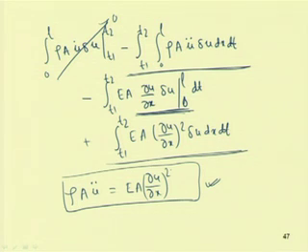So, in today's class we have taken several examples using Lagrange and Hamilton principle to derive the equation of motion. We have derived the equation of motion for a single degree of freedom system, that is the simple pendulum, for a 2 degree of freedom system, that is a double pendulum, and for a continuous system, that is the longitudinal vibration of a rod.